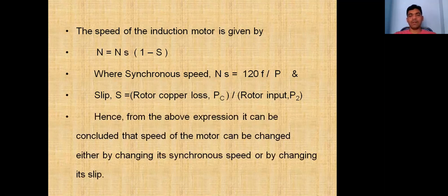Hence, from the above expression, it can be concluded that speed of the induction motor can be changed by either changing its synchronous speed or by changing its slip.